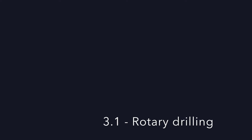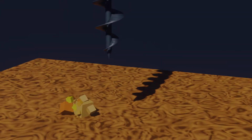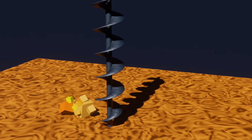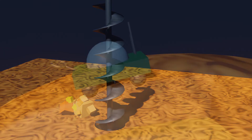Rotary drilling is considered to be a more traditional form of drilling, as it is a commonly used method, both in existing space missions and here on Earth. The petroleum industry on Earth offers a fundamental level of experience that can be used to design space missions with rotary drilling applications. Rotary drilling involves a drill bit that is rotated and pushed into the ground. Thrust and torque are exerted simultaneously.